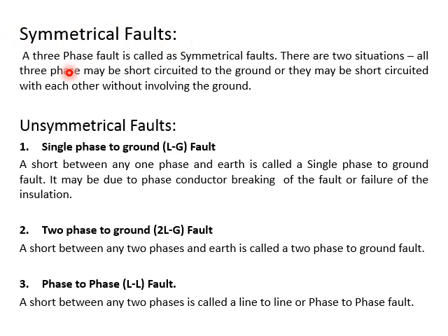Symmetrical faults. A three-phase fault is called a symmetrical fault. There are two situations. All three phases may be short-circuited to the ground, or they may be short-circuited with each other without involving the ground, as we discussed.